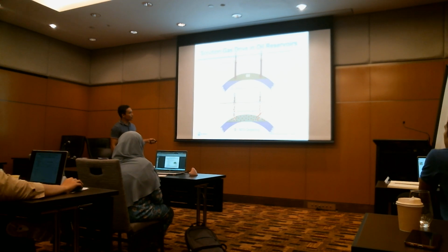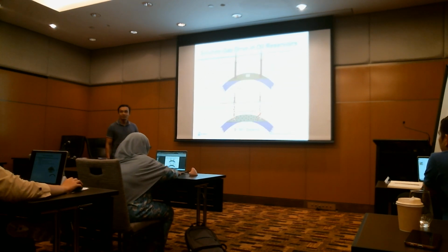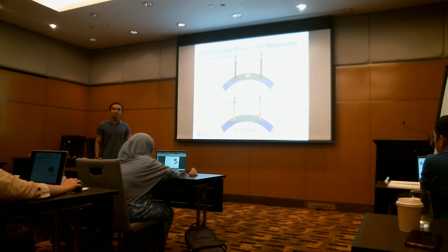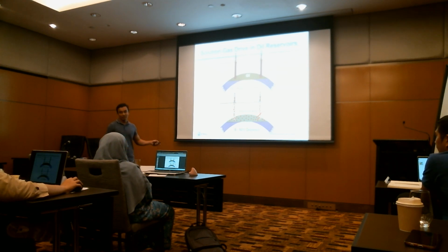See, solution gas. So in the event that your water drive is weak, then you would have the solution gas become the dominant drive. In each drive mechanism, like I said earlier, combination, there will be a dominant drive. In the case of a weak aquifer, this will be the dominant, but with a strong drive mechanism, this will be the secondary.